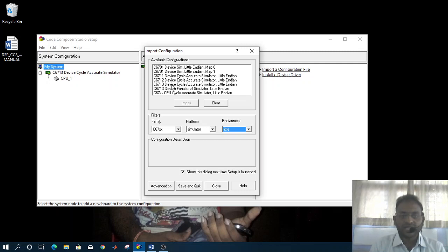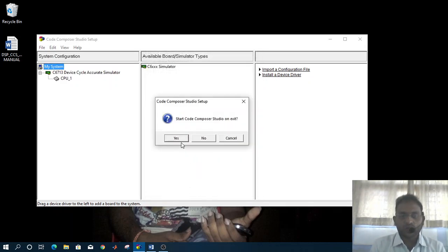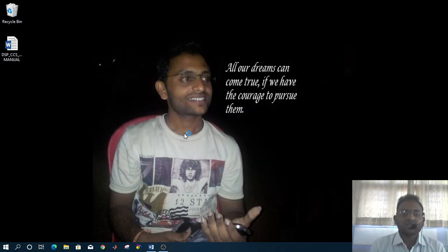So I am going to select the C6713 device cycle accurate simulator, and I would like to import that to my project. So I am importing it, and let me save and quit. Upon saving and quitting, it is asking me to start Code Composer Studio upon exit. So I just start that. I am starting Code Composer Studio now.